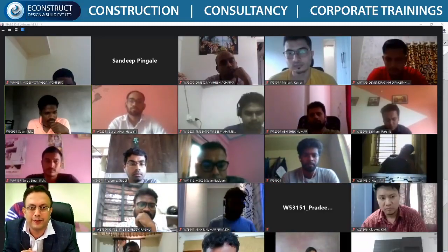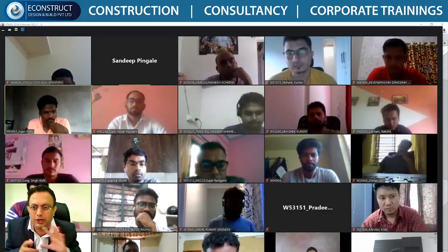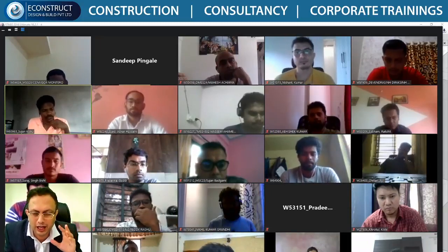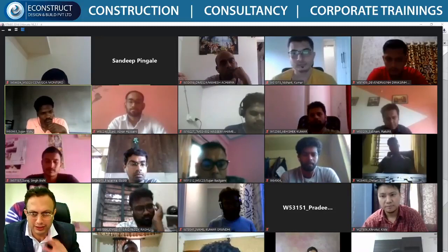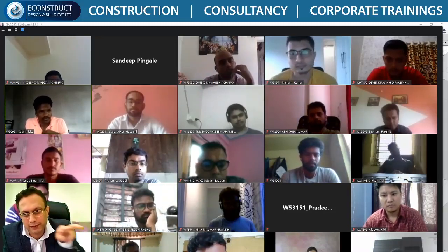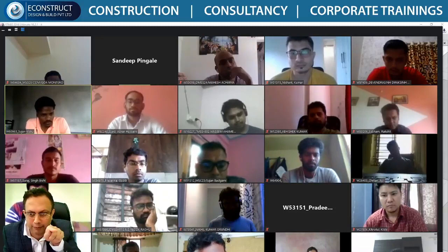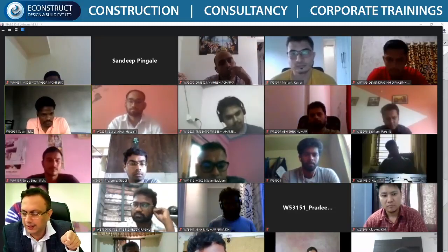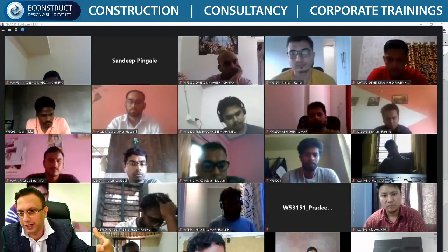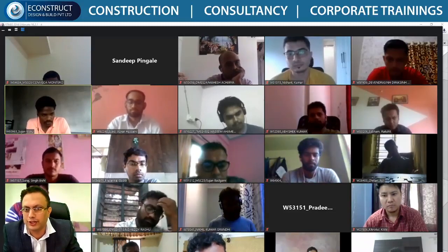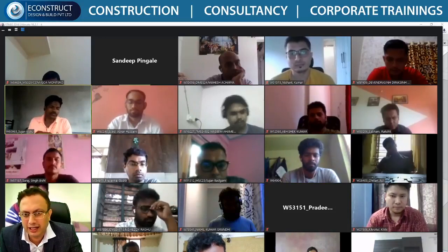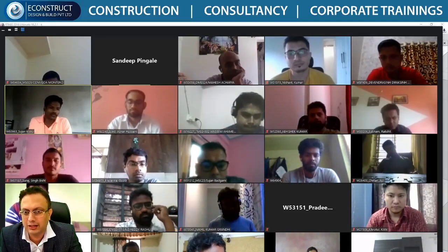Alright, so what I would like to suggest is that you give the fixed option and run the analysis if you are getting confused, and then check the behavior: which is primary, and how the force is transferring from primary to secondary, from secondary to primary, and from primary to the main frame elements, and then it goes to the columns and to the foundation. So load path decision is a little difficult at the initial phase of the career.